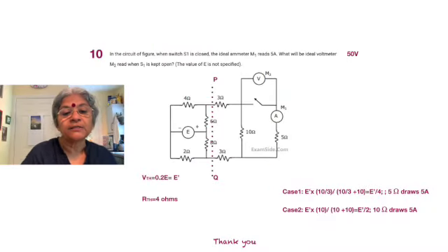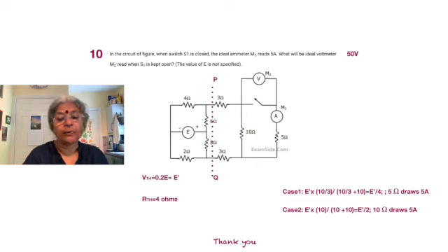Now this 4 ohms is going to be in series with another 3 ohms and 3 ohms and a parallel combination of 10 and 5 ohms, in case number 1. So case number 1 is equal to having a voltage across the 10 ohm and 5 ohm in parallel, and it's a potential divider there. We are having E dash multiplied by the combination of 5 and 10, which is 5 into 2 by 3 or 10 by 3.